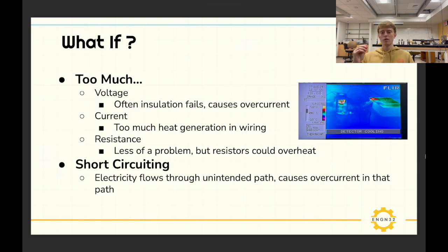All right, so this slide is all about giving you intuition about what happens if I have too much or too little of the things we just talked about. So what happens if I have too much voltage? If I have a transistor, and that's something that we'll talk about next time, so if you don't even know what a transistor is yet, that's fine. But basically transistors, or at least MOSFETs, have gates. And if you apply a very large voltage to the gate of a MOSFET, then you may short the gate to the rest of the MOSFET, the body of the MOSFET. And if you do that, then you will destroy the MOSFET.